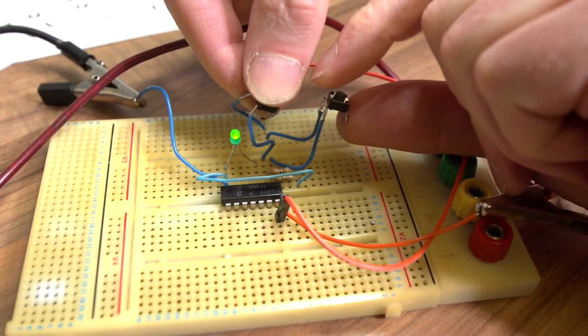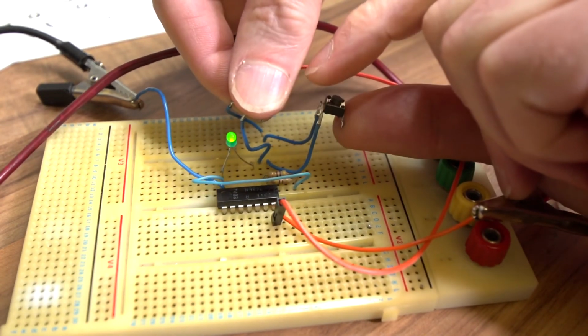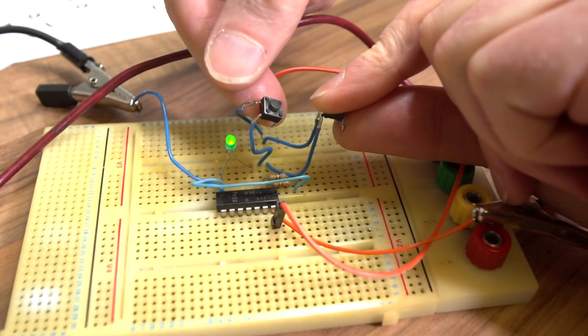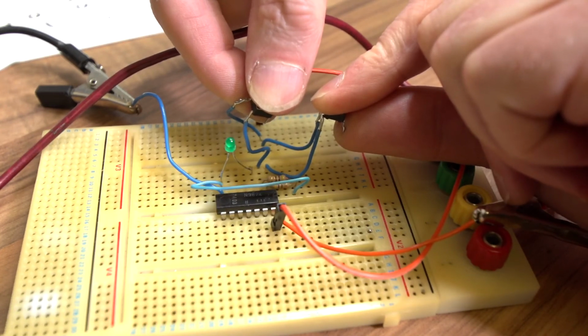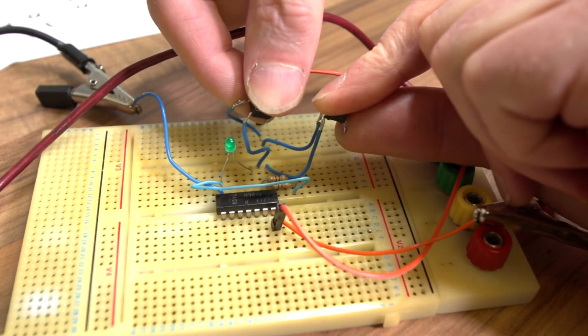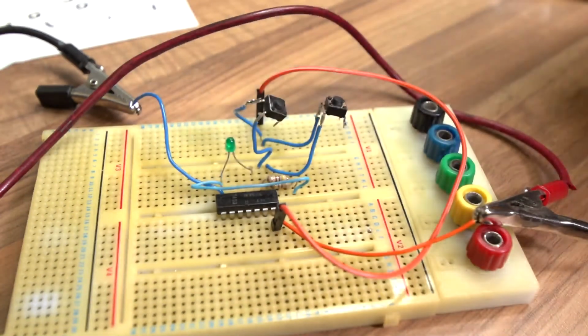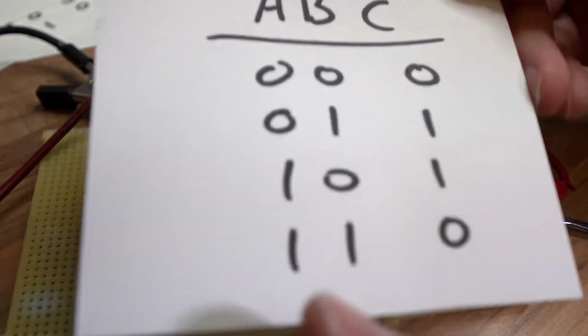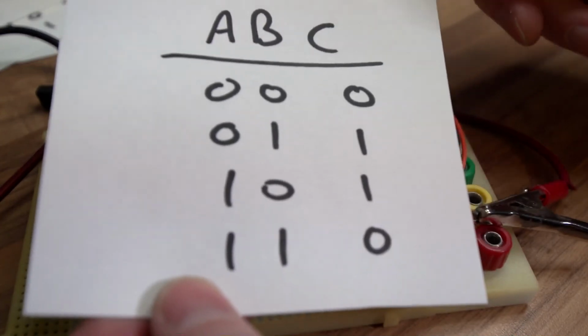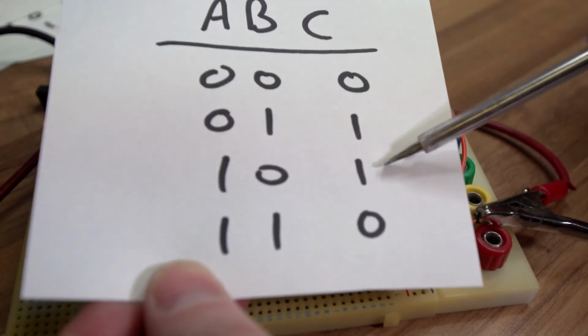Release the other switch, so either one, which creates a difference, that's our difference indicator. Either one of them, but not both, that actually illuminates the output. And also if I release both, it's also off. So that's exactly correct. That's the exclusive OR doing what it's meant to do. Only when there's a difference, we get a 1 output.